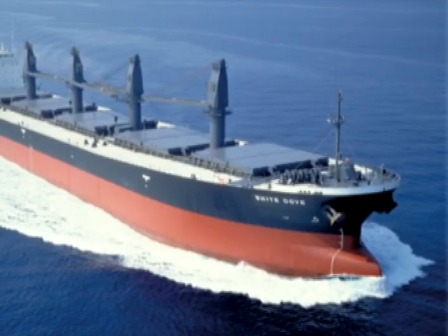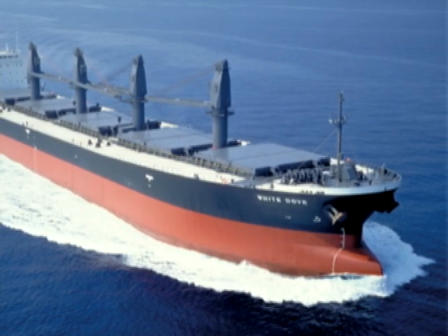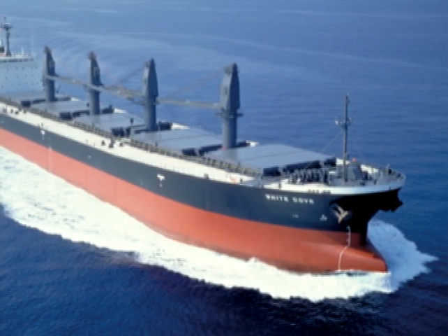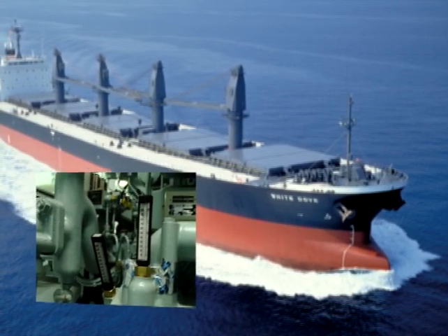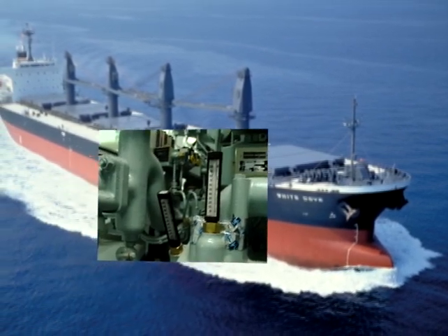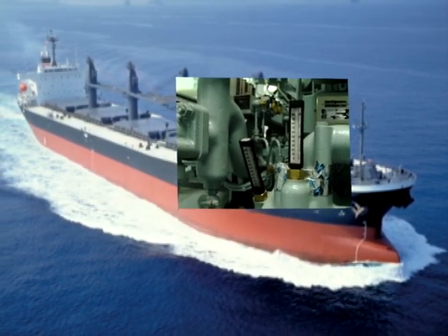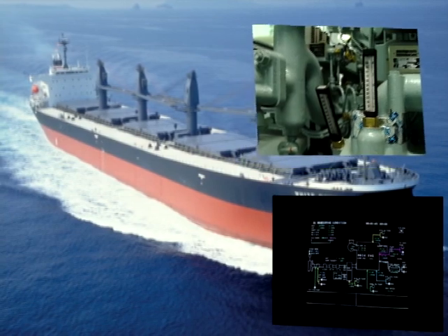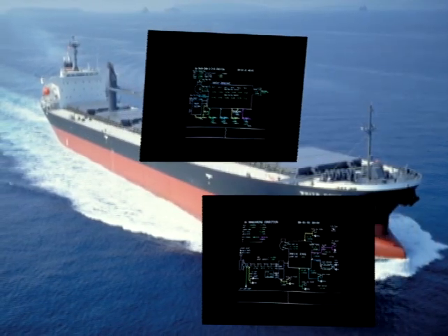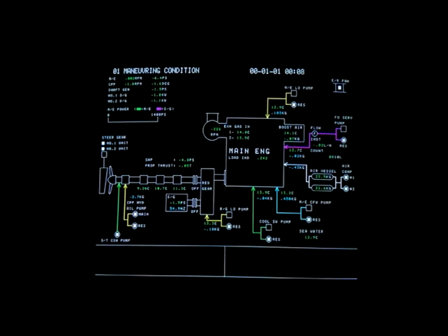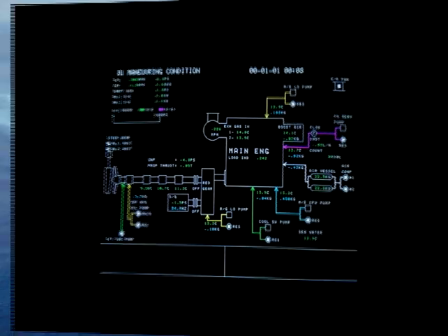The engineer should have temperature information for fuel oil, lubricating oil, exhaust gas, seawater, fresh water, steam and air, and so on. When inspecting the engine room, temperature is measured using an analog thermometer connected directly to the piping. On the other hand, temperature data measured by electronic thermometers is collectively monitored and recorded in the control room. There are different types of temperature sensors. Here, let's look at some of them.